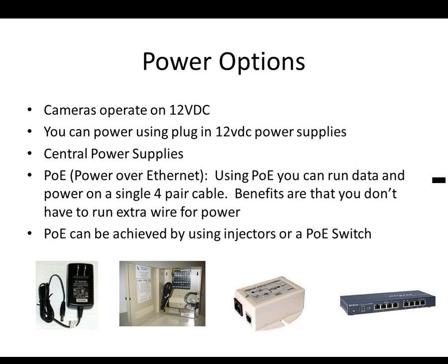Here we go over our power options. The cameras operate on 12-volt DC. You can use plug-in power supplies to power the cameras separately. You can also use central power supplies, as you can see in the picture with the box in the middle.